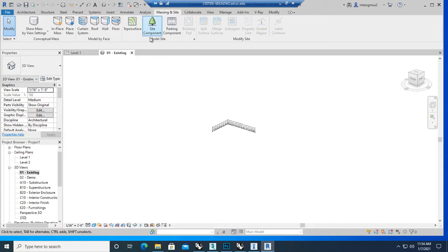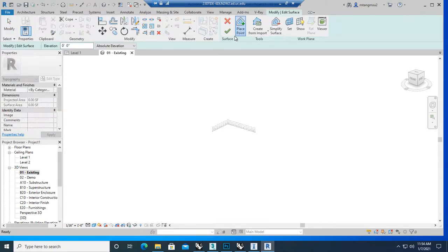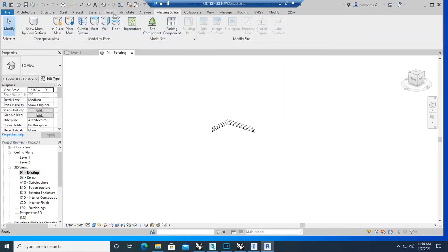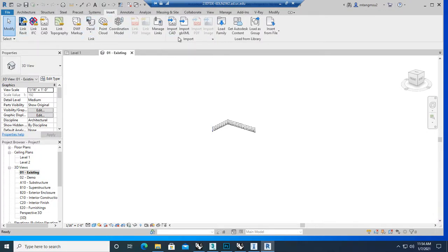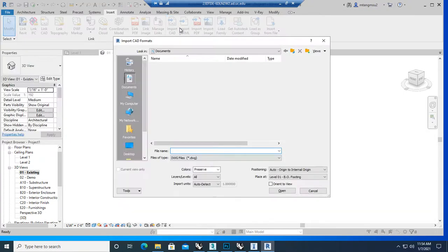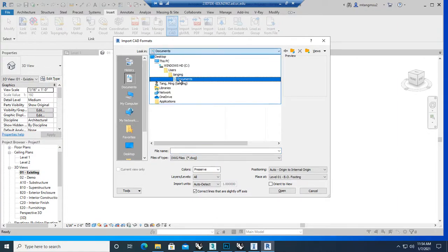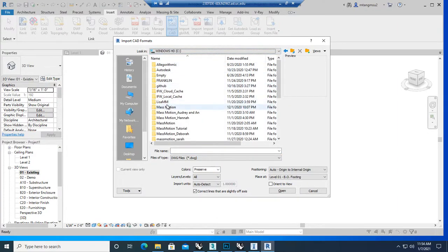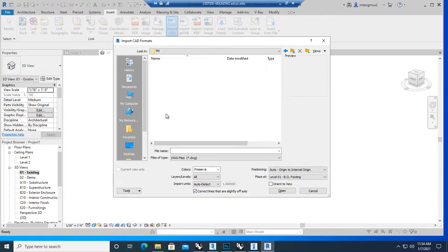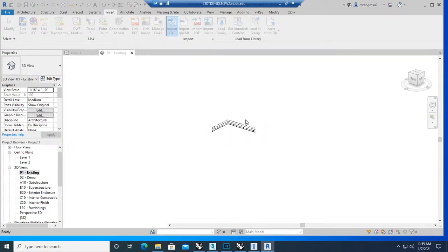So here in the Massing side, I will go to Topo Surface, and I will pick a surface from import, right? But before that, you have to import the file first. So let's cancel that, Insert. There are a lot of files you can put in. I will bring in a CAD file, which is DWG, DXF, and I will point to the file I just generated. I put them in my TM folder. I believe that came from Rhino, right? So here's contour DWG. Click open.